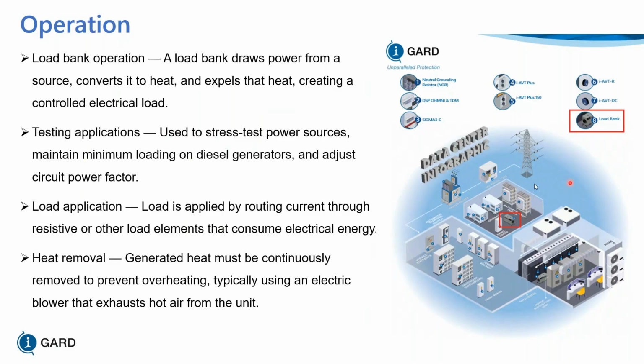Test applications are used to stress test power. Again, you're going to put your power source through some severe power profiles to ensure that it can react under any particular load profile and make sure that it's going to be stable. The most famous type of test is a load rejection test. So what happens when you have a load rejection test? You have a lot of load, you shut the power off, and what happens to your power source? Can it maintain that?